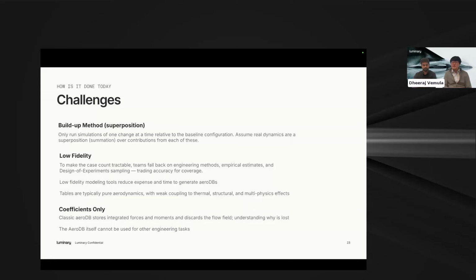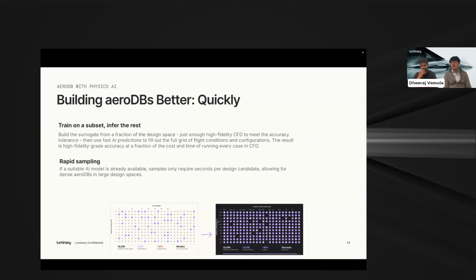And so if we go to the next slide, one of the things you can do, once you have this physics model, is use it as a data engine. You can create specialized models, for example for a specific portion of your flight envelope. Maybe you predict the forces and moments only in that small subset. You can get equivalent accuracy; it just takes a lot of data.